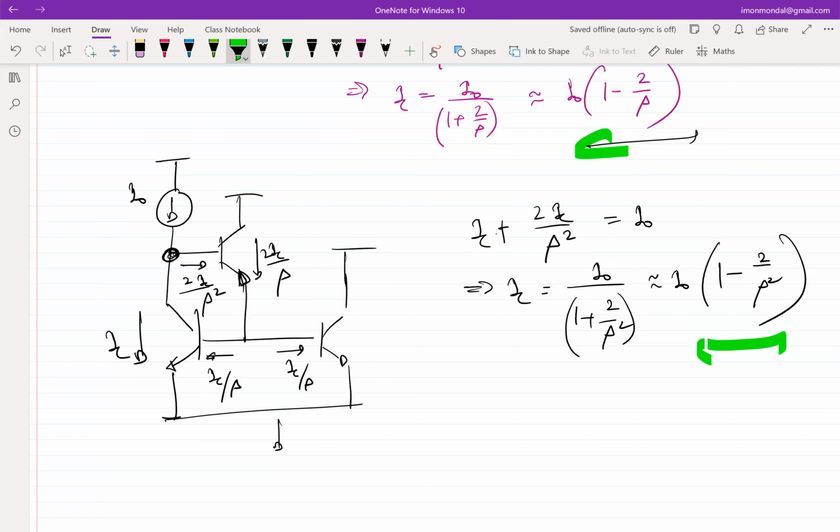You mean in a BJT circuit, you want a MOSFET? Yes, you can. There are some BiCMOS technologies where you can configure both MOSFETs and BJTs. By the way, that is not a very common technology. In most technologies you can have either a MOSFET or a BJT, but there are super expensive technologies where you can do both. There you can do all sorts of stuff.